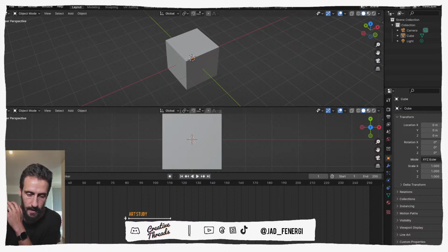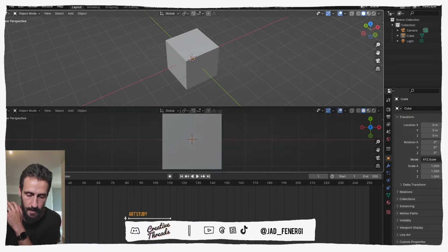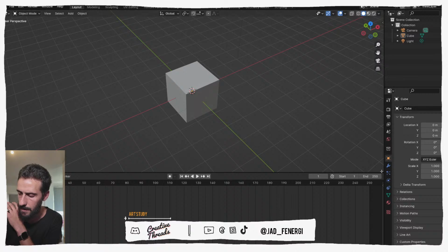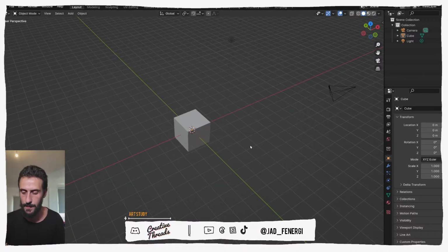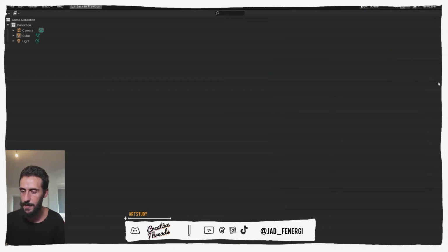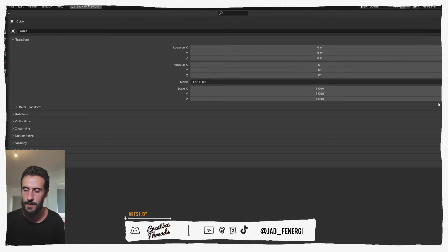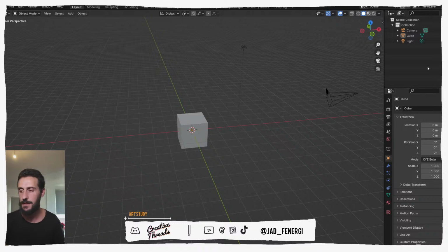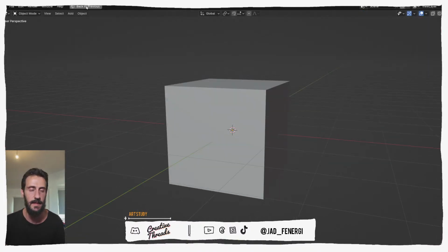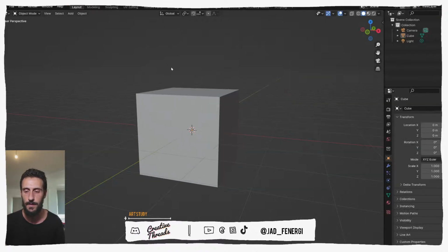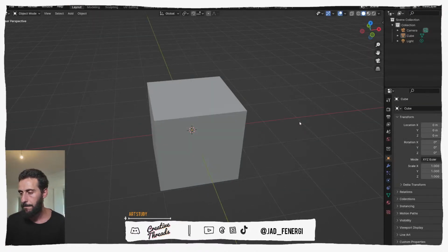And if you click and drag, you can cancel the other viewport. And if you press Ctrl space in one of the viewports, you expand it. So on any viewport, you can press Ctrl space to make it full screen, so you can check it out more, and you can go back to the previous layout with Ctrl space. So this is just a quick rundown.